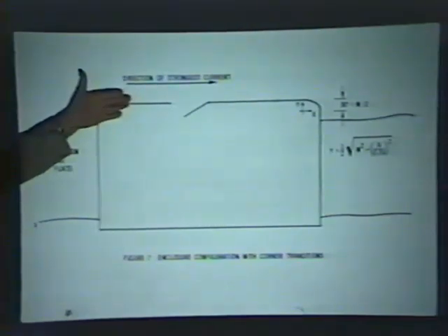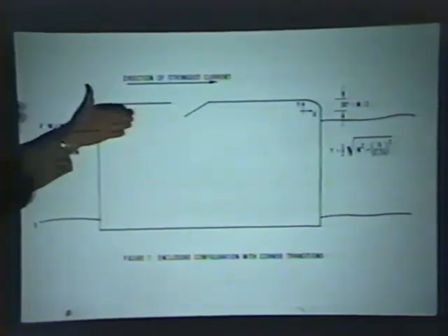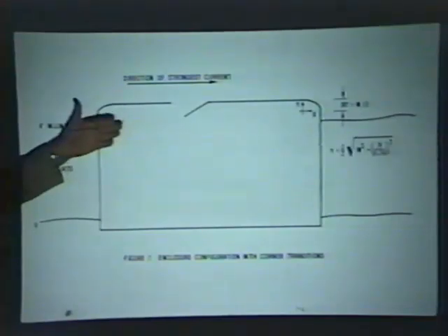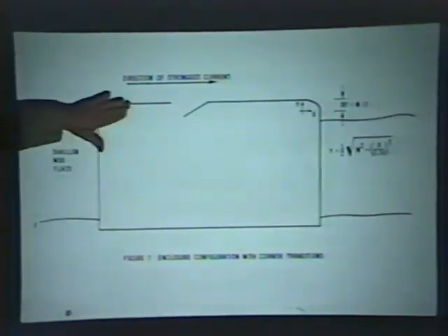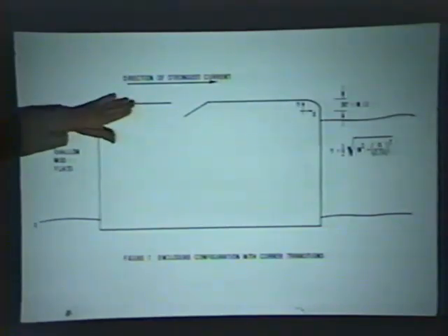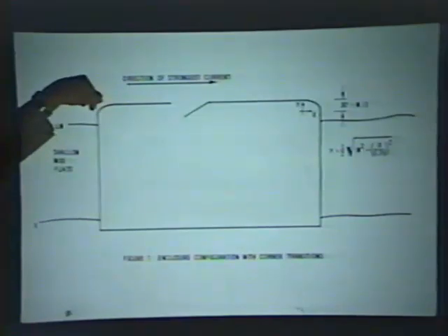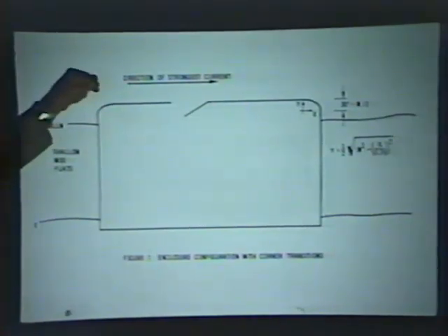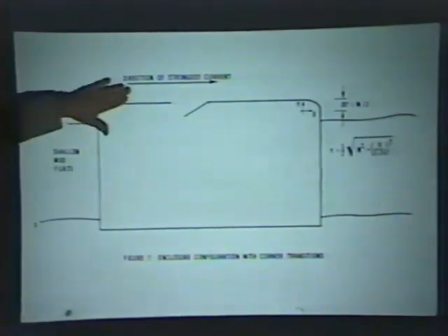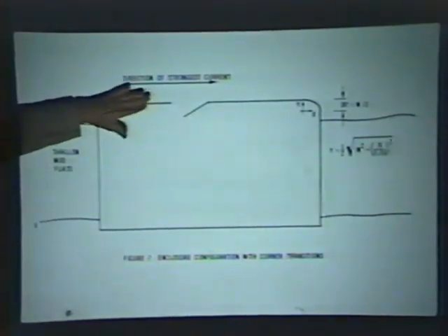So part of the process of designing a wall of this sort is to calculate the height of the waves that you get 1% of the time, or whatever they're willing to get, and estimate the height of rise of the waves. We discussed this a lot in 260, so you can handle that all right. The problem is that every foot rise in the height of the wall costs a lot of money.